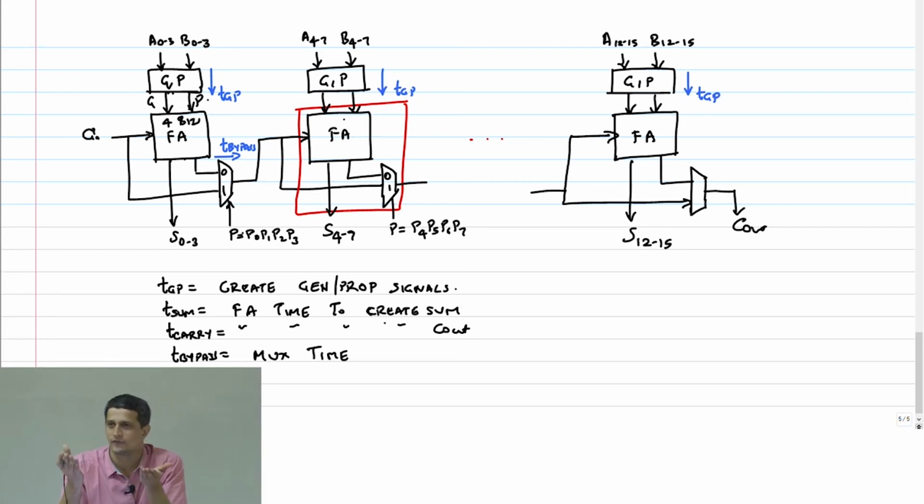You agree that it's very similar to the ripple adder here. Any bit in between being in generate mode cannot be the worst case delay, because that will have a lesser time to propagate through now. Correct? So therefore, all these adders in between have to be in propagate mode. Right? I have 4 adders, so I'm going to put all of that here.